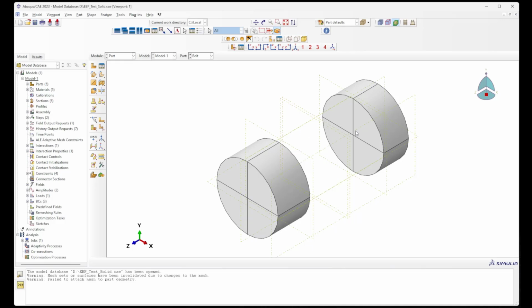Instead of creating the bolt head and the bolt nut as separate parts, because if you do that, this will mean more work for you later on when you are moving this to the assembly. You will need to start positioning both the nut and the bolt head separately. But now if I have it in one part, it's exactly the same. They will be behaving separately because they are not connected, but at the same time, you just deal with them as one part.